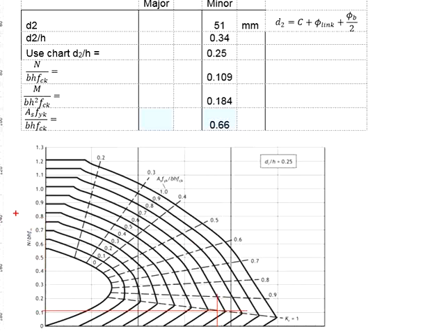You need to generate a number for N per BH FCK. The N is the absolute, which is given as 147.36 kN, BH is 150 times 300, and FCK is equal to 30. Therefore, you get 0.109.